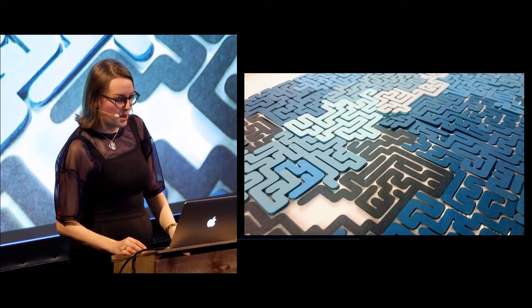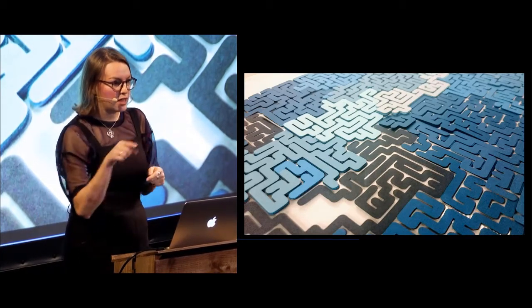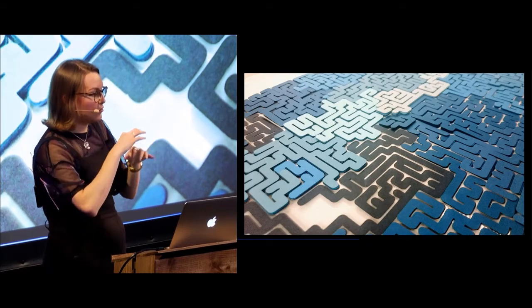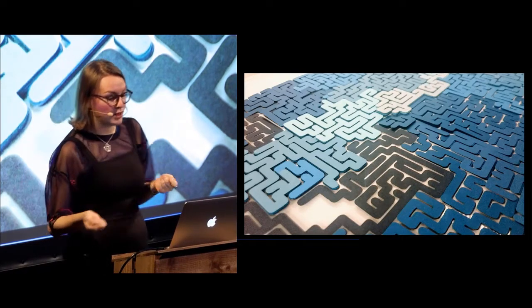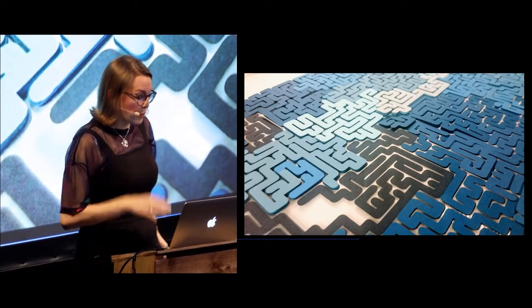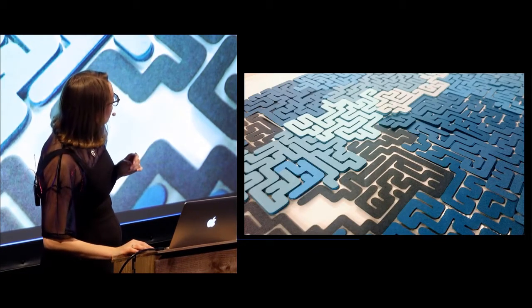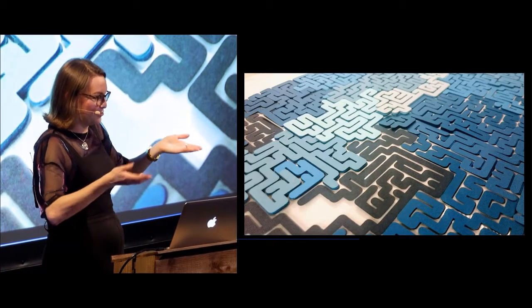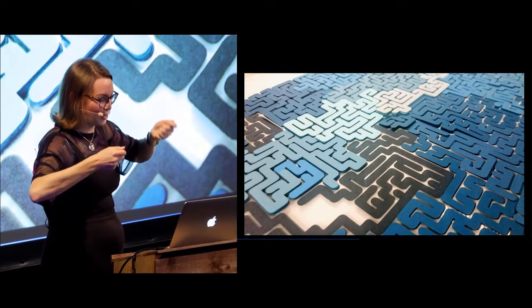Would really recommend that. Paper is really fun to laser cut because you get very, very neat edges, and because it's so thin, it takes barely any time at all. So you can make very complicated, intricate patterns, and it'll happen really quickly with basically zero effort. The downside is paper's really delicate. I didn't really think about that when I made mazes, but trying to pick up a sheet where everything only connects to one thing is very, very difficult.